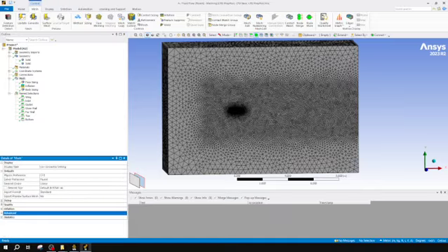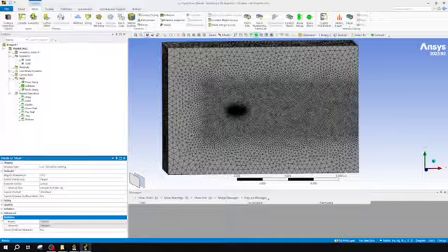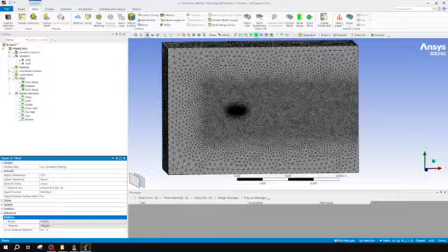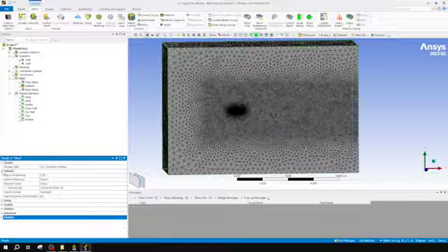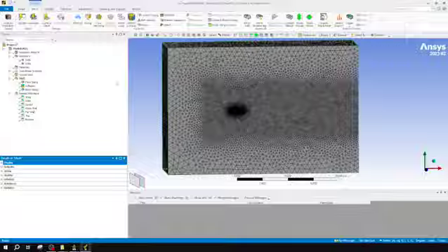The last one that's kind of important for us is our statistics. So this mesh has about 3 million cells, if I read that right. Yeah, just shy of 3 million cells, or elements as they call them. I think for my actual study, I have more like 5 million, if I remember off the top correctly. So it's not bad, but again, I'm probably about 2 million cells short of a good mesh. But yeah, so that should have saved and figured out our mesh to a standard we like.